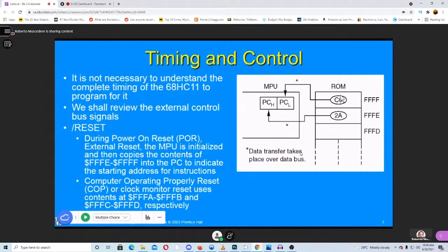Now, another thing to note about when the system resets, and I'm pretty sure about this, is there's no guarantee on the values of the registers internally. So what is accumulator A going to be, or what is accumulator B going to be? They could be all something random. So you have to do something with those if you want to use them. Assuming they're 0 is probably very bad to do. So you would formally set them to 0 and then use them, for example.